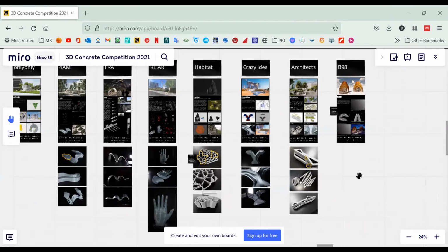I have a last question, please. About support structure: can the support layers cross the main layers or just a little bit touch them? It should touch. It shouldn't cross, because then you will get some bumps. The support is barely touching.